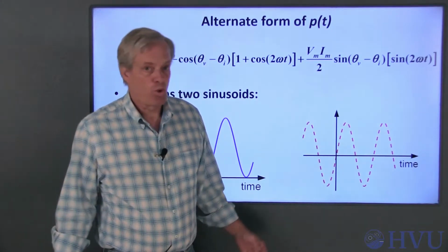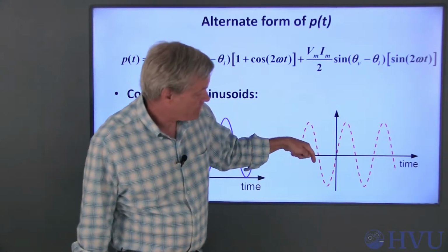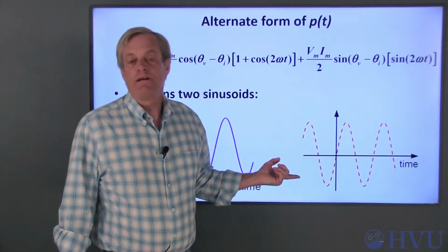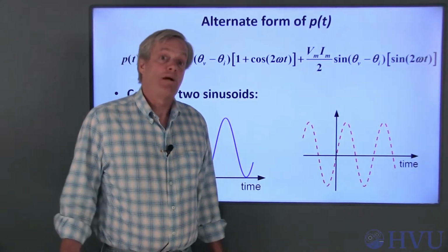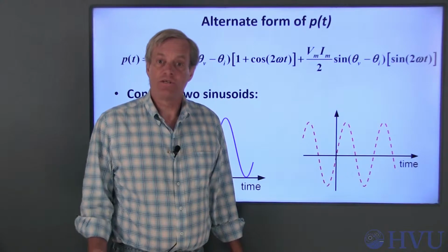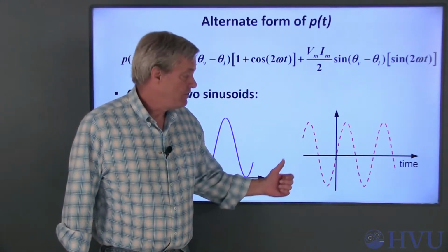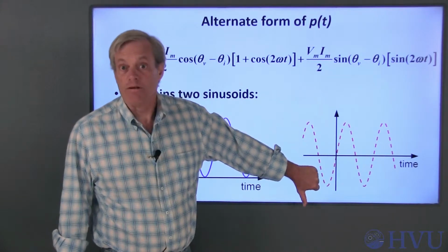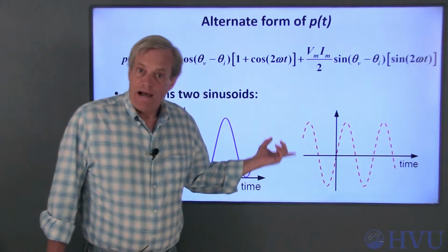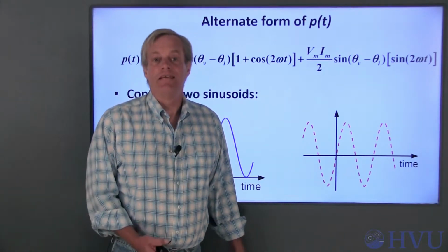The power that's absorbed when the power is positive is exactly balanced by the power that's generated when the signal is negative. This signal corresponds to the reactive power, and it's representing what the energy storage elements in the circuit are doing. Capacitors and inductors don't dissipate any energy. All they can do is store the energy and then return it to the circuit, which is exactly what this sine wave is doing. The reactive power, then, is representing the energy being stored and released by the energy storage elements in the circuit.